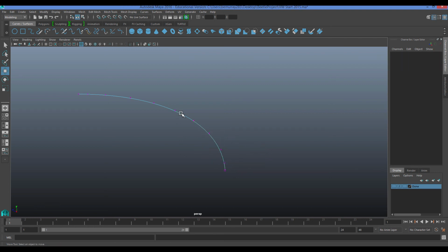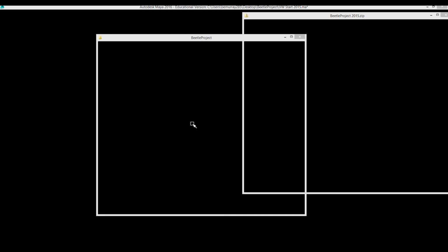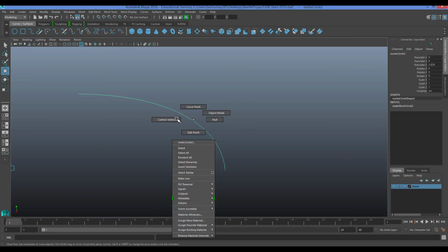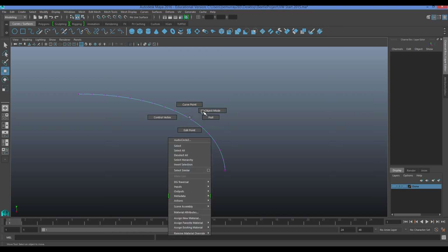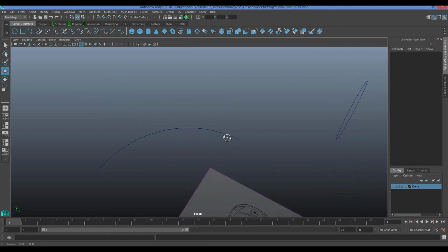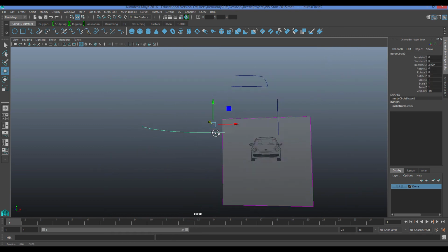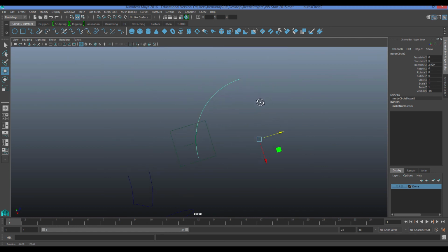In this case, if I have my circle, which currently has 8 sections, and I change that to 16 and click, what you'll find is that I have a lot more detail sections to work with. So circles can be used really quickly for quick arcs, half degrees, and also full round shapes.